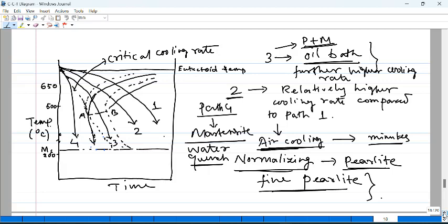It is very different in the sense that the change in the crystal structure comes about by a very different mechanism. In the case of the pearlite transformation, we know there is enough time for diffusion to occur, and therefore the atoms can move and arrange themselves into a different pattern to come up with a new structure for the new phase.